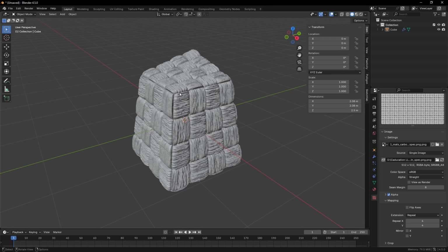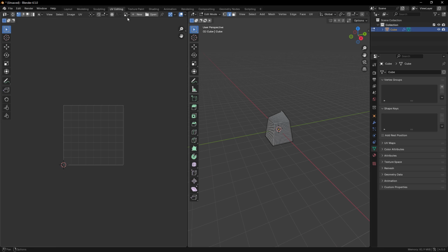And you'll notice it actually looks pretty good. Like we do have the fabric weaved over the edges and corners, and it's stretching. It's kind of shrinking on top and stretching on the bottom. Now, this is because by default, this object is automatically UV unwrapped. So if we're in UV editing, hit A on the keyboard to select all. This is the default UV unwrap. So it already knows that it's essentially dealing with an unwrapped cube, even though we've deformed it slightly.